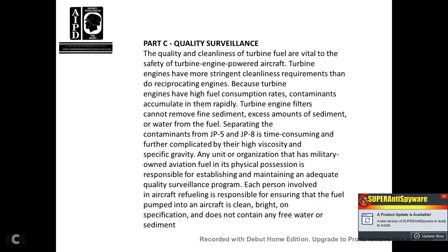And Part C, quality surveillance. The quality and cleanliness of turbine fuel are vital to the safety of turbine engine powered aircraft. Turbine engines have more stringent cleanliness requirements than reciprocating engines because turbine engines have high fuel consumption rates. Contaminants accumulate rapidly.